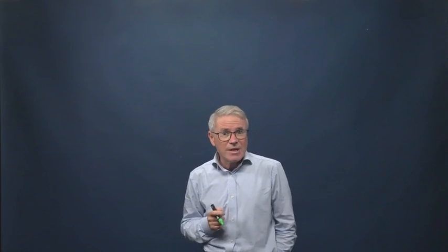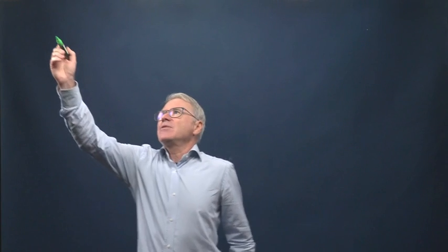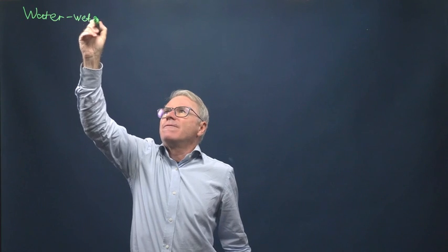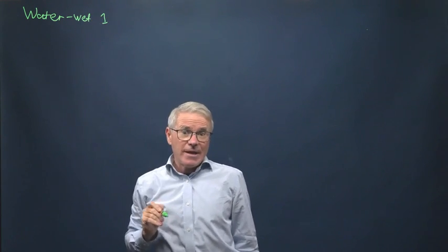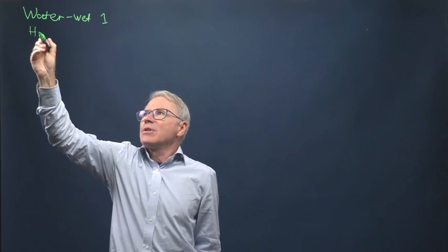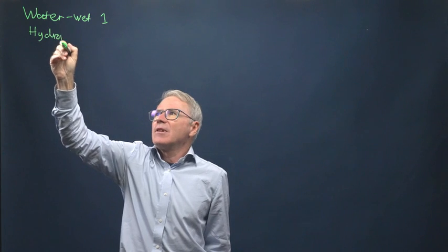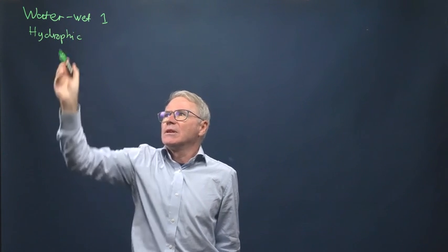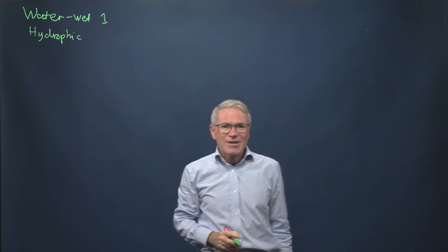But let us start with relative permeability itself, and I'm going to look at three different conditions. The first one is a water-wet medium. So phase one is the wetting phase. We can also call this hydrophilic, right? Likes water. Okay, that will be the first case.